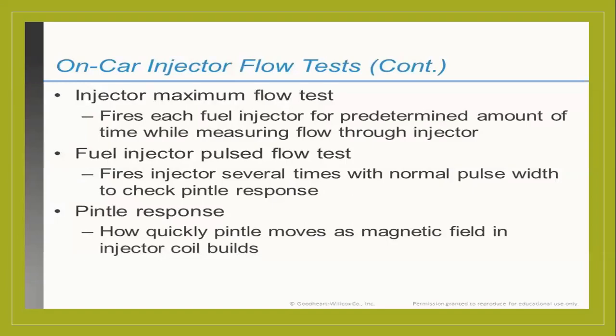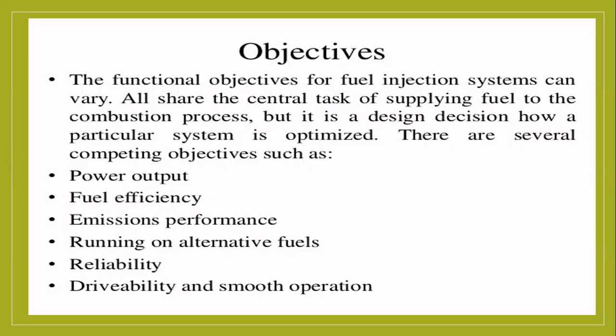There are some tests you want to check: the spray of the nozzle, injector maximum flow test, fuel injector pulse flow test, and pintle response. These are the injector nozzle tests. I will tell you. Okay, we will come to the objective of this